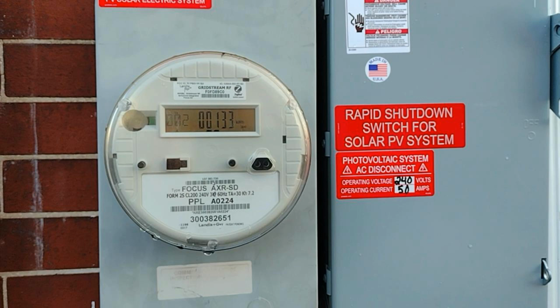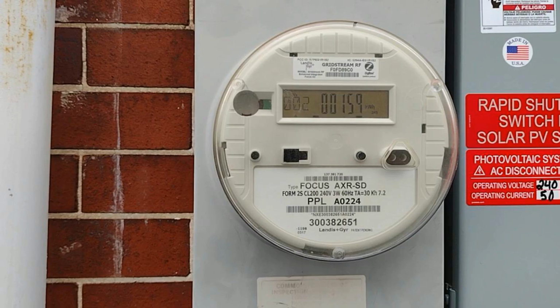This is how much overage you've generated and pushed back onto the grid. Now, if you don't have some kind of generator on your property and you have a reading on this, that could be a problem, believe it or not, because if somehow you're pushing electricity onto the grid and you don't have a transfer switch set up, you could actually electrocute somebody in the event of a power outage. That's just not good.